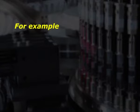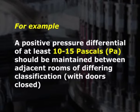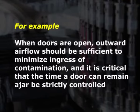For example, a positive pressure differential of at least 10 to 15 pascals should be maintained between adjacent rooms of different classification where the doors are closed. When the doors are open, outward airflow should be sufficient to minimize the ingress of contamination, and it is critical that the time a door can remain ajar be strictly controlled.